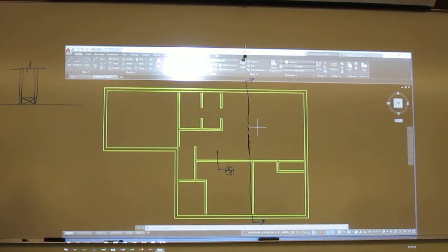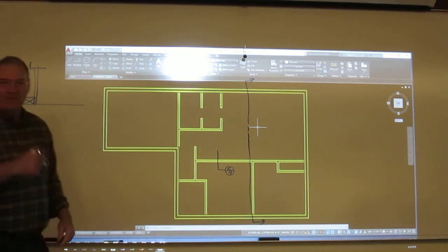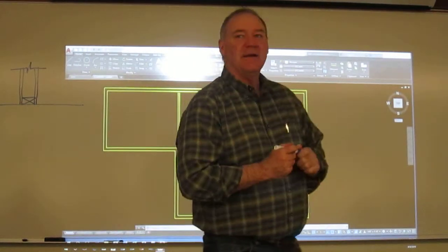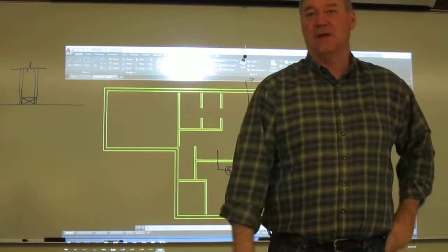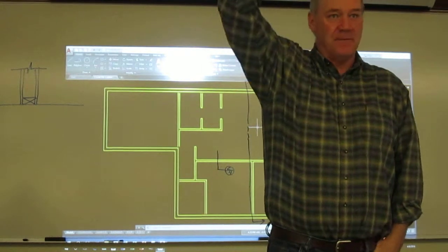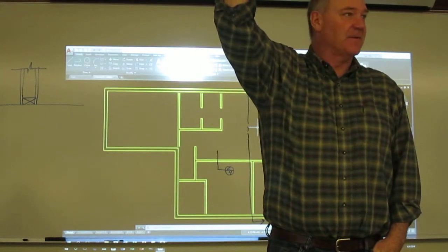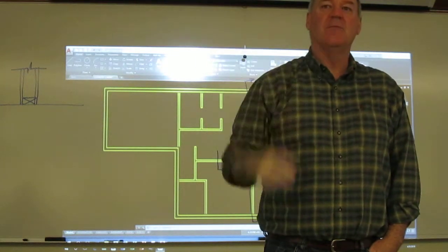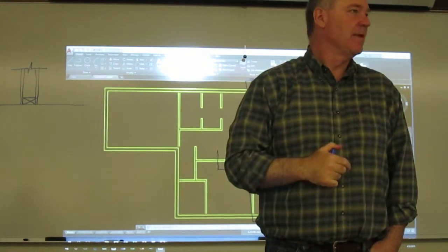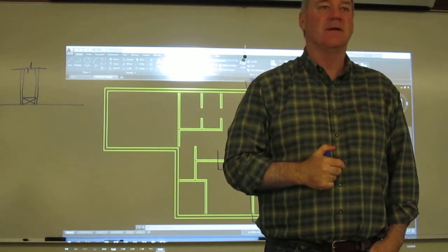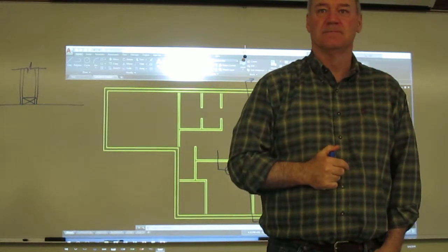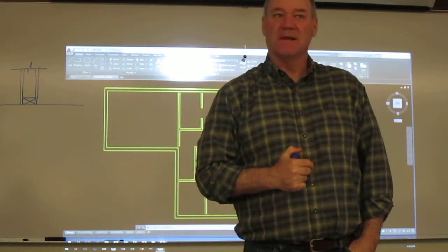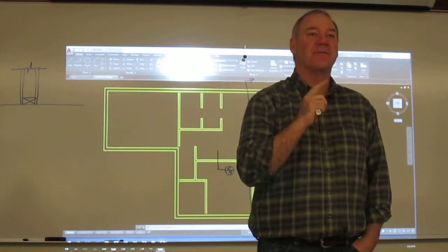If you remember back in chapter 4, we had that little chart that we've referenced several times that we have to assume that it's clay. It is one floor that we are supporting, correct? We're supporting the floor right above here. That's carrying for the first floor above the living room. In clay, what is our minimum size of footing that we can use? What's that? Is it 18 inches? No, it's not 18, not for one floor in a wood frame structure.